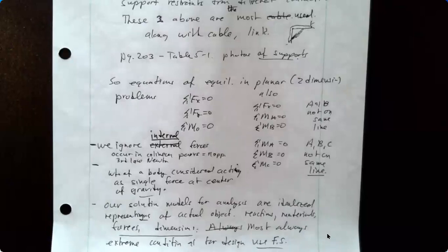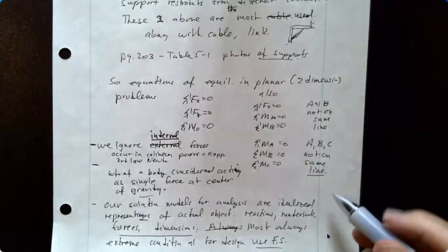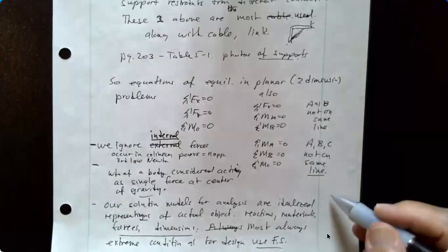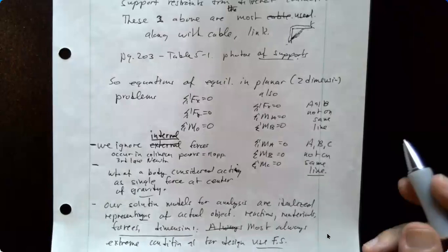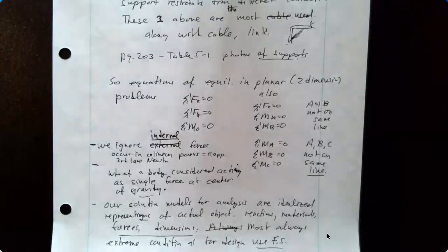And the design didn't account for that. We didn't know those loads were going to be there. But what we do use are factors of safety. So if you design a load you think is going to be 1,000 pounds, let's say, and your factor of safety is 2, you design it for 2,000 pounds. And it accounts for deterioration, it accounts for change in use.